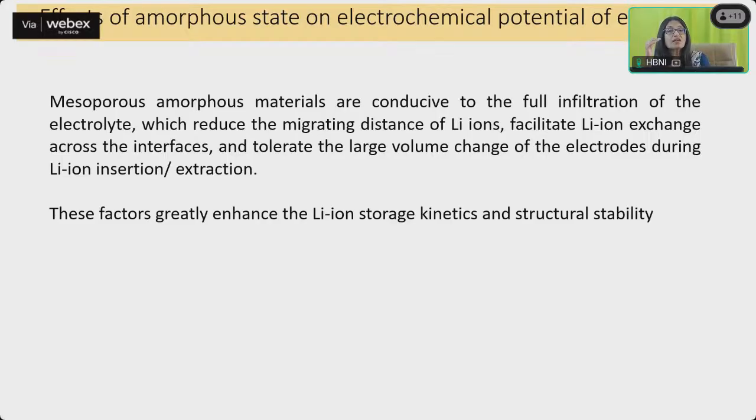Then your efficiency decreases, because more SEI formation means more lithium is not getting back into the reversible charge discharge reaction. More and more lithium is getting lost, so your specific capacity is going to decrease, and your coulombic efficiency is going to be much less. So again, you have to strike a balance on how much size reduction you do, to ensure that your SEI is formed but your coulombic efficiency is not compromised to a large extent.